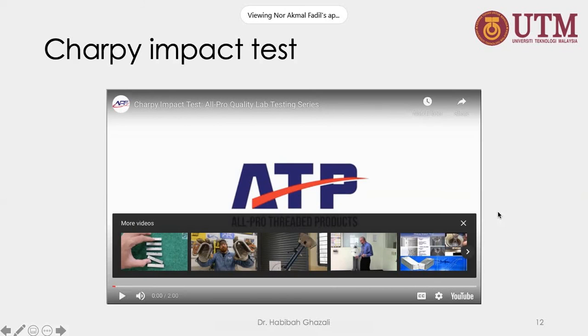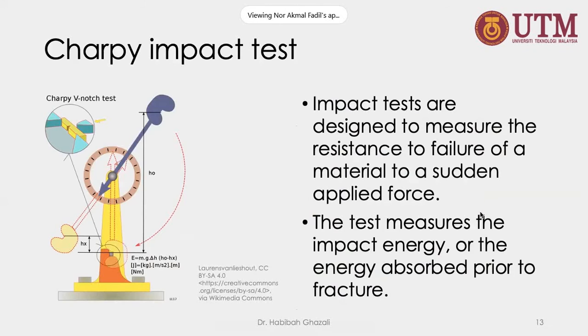Okay, that's how the impact test is conducted. So it designed the specimen at a standard specimen size by following the standard, and they give the loads. It depends on the environment that you want to test, whether at room temperature, meaning there is no influence of temperature, or at very low temperature, because we want to see the ductile to brittle transition. Basically, brittle properties are obtained at a low temperature.